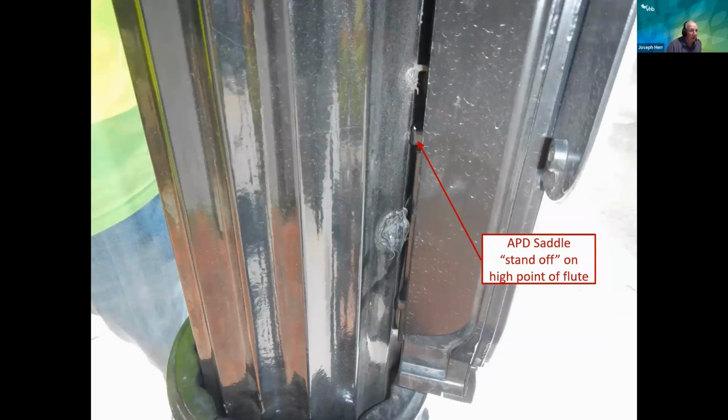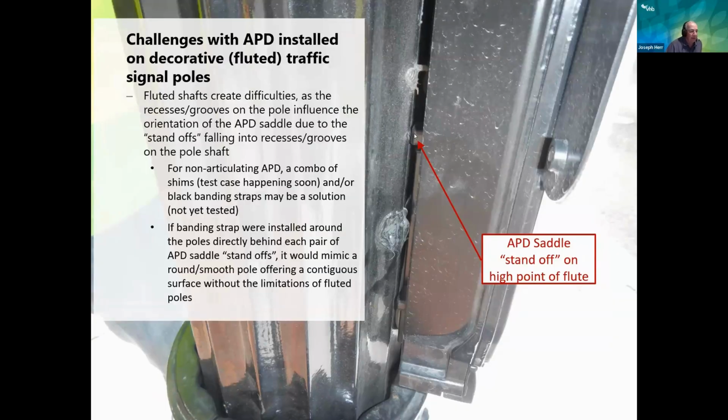When you have a fluted pole, the angle of your button is going to be dictated by the orientation of the grooves on the fluted pole. So sometimes there are creative ways of putting standoffs in there, or maybe putting banding straps in there and so on. So if you're going to call for, as a designer, that you can have fluted poles, just understand that there may need to be a construction note on the plan, or some understanding that it may be a challenge for the contractor to meet that without special accommodation for the button to the pole.